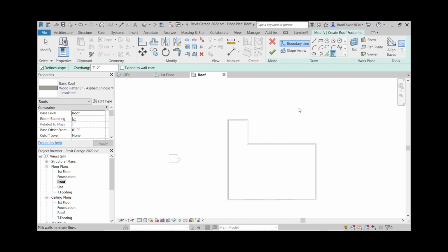The first thing to understand when you come into this roof design is that it's like a separate little program. If you can see the highlighted green section, these are all roof tools. I'm basically doing a sketch inside of here. The default sketch mode is to pick walls.